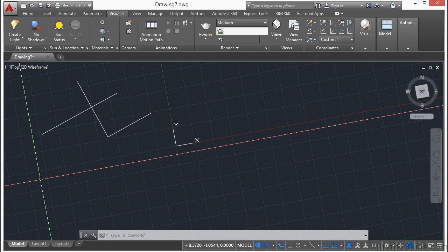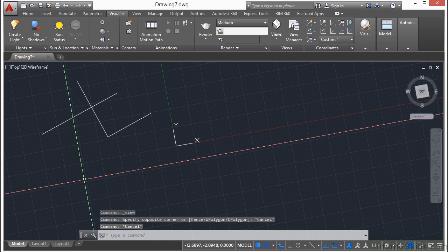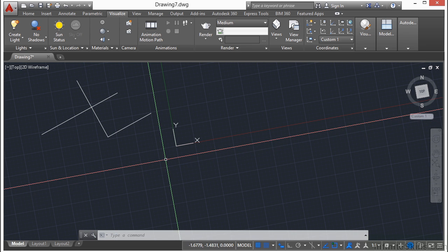Using a rotated UCS is great for isometric drawings, as you could probably see. But AutoCAD does have a specific mode for that called isometric mode. This allows you to toggle your rotation very quickly and is actually quicker and easier to use than UCS.